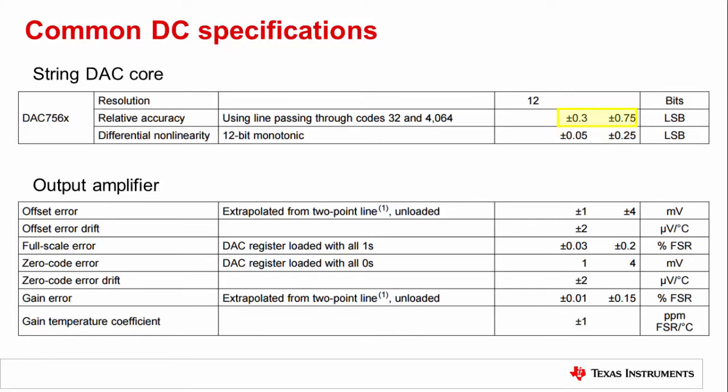The INL is typically 0.3 LSBs with a max of 0.75 LSBs. This spec scales at 2 to the power of the difference in bits. Again, for the 16-bit case, the number would scale up to 16 times the original, giving about 5 LSBs typical. Remember that this is just a shorthand way to estimate the difference between the specs of 2 different resolutions.